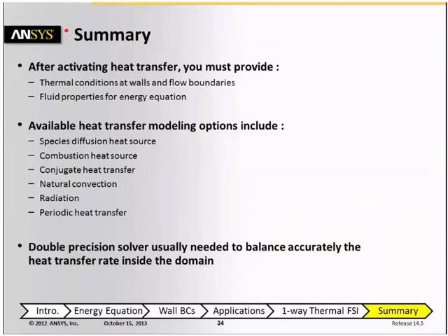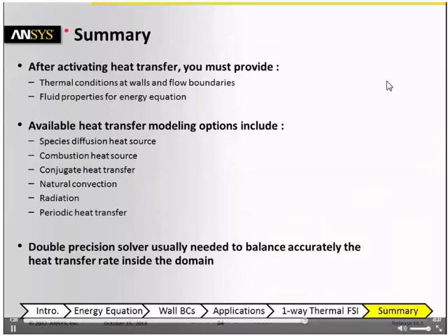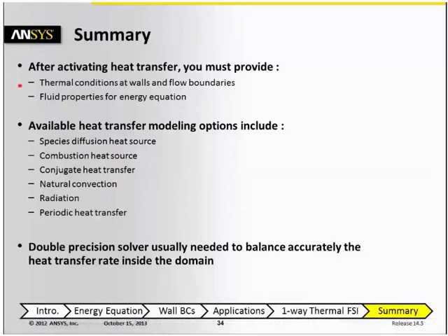So finally, to summarize the most important points in the lecture, after you activate heat transfer, you have to provide thermal boundary conditions at walls and flow boundaries, and also fluid properties for the energy equation.